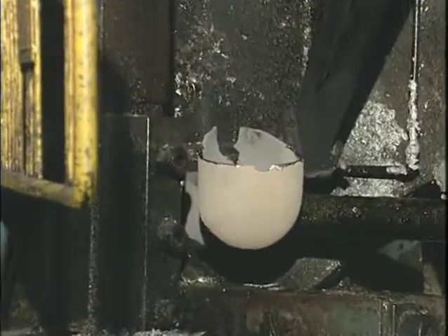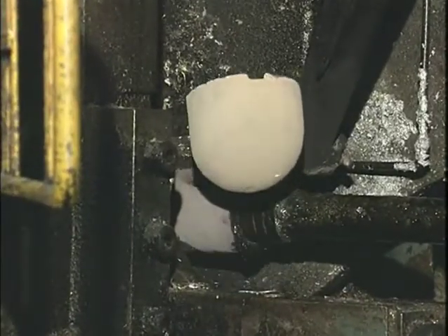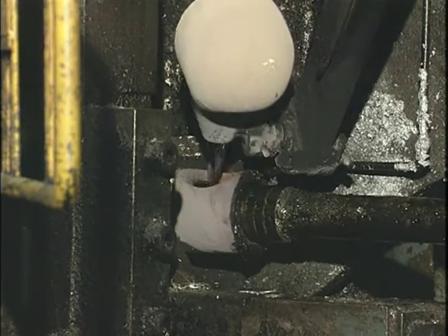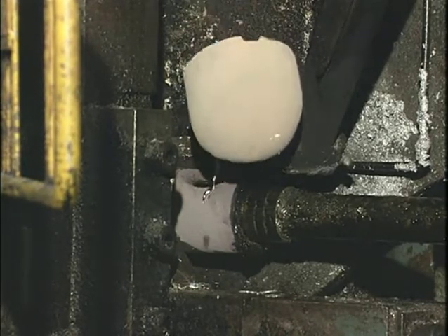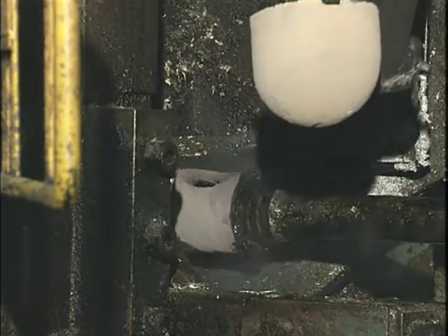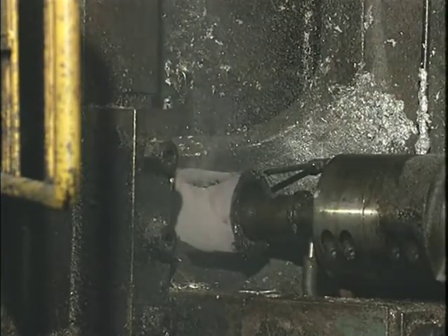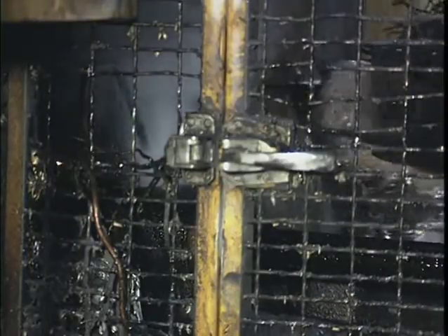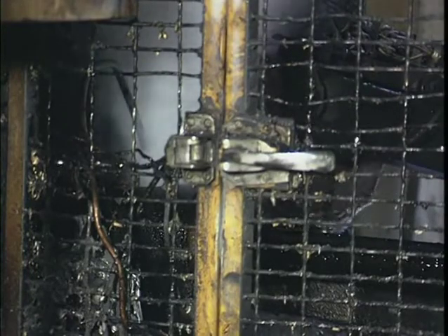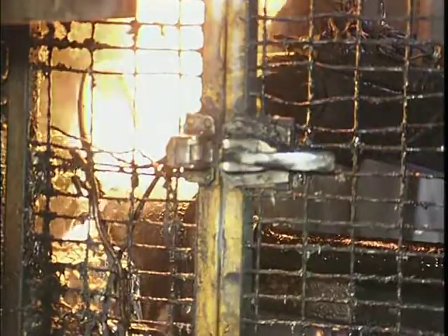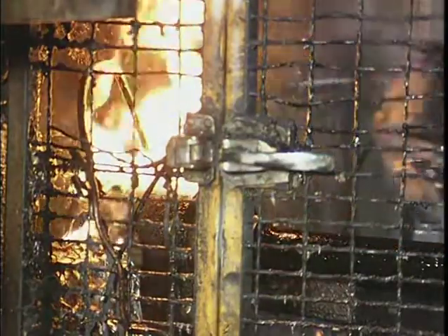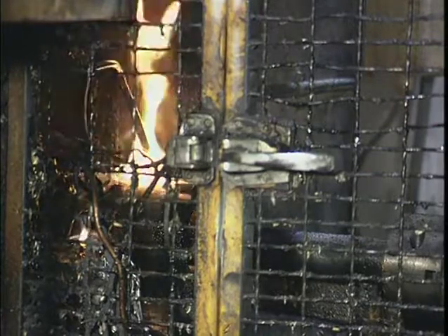The charge is poured ahead of the plunger tip through a pour hole in the shot sleeve. As the plunger advances, it closes the pour hole and drives the molten metal into the die. Injection pressures may range to 10,000 pounds per square inch or 69 megapascals for aluminum and magnesium, although some machines can provide still greater pressures.